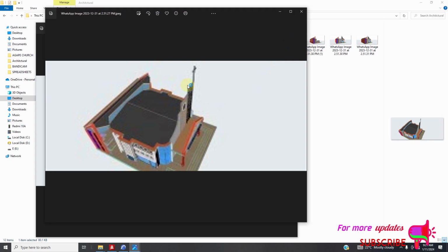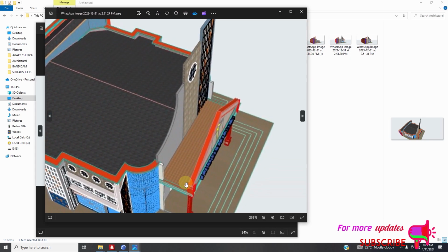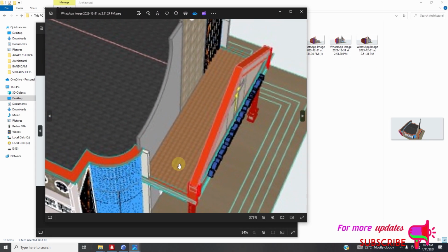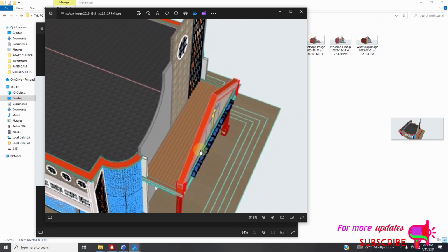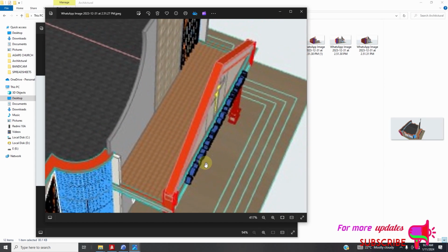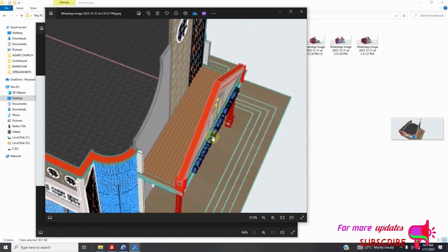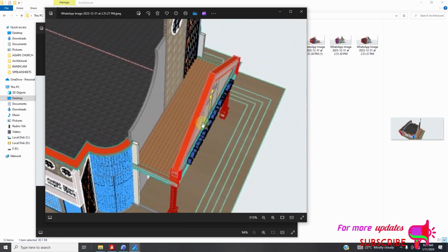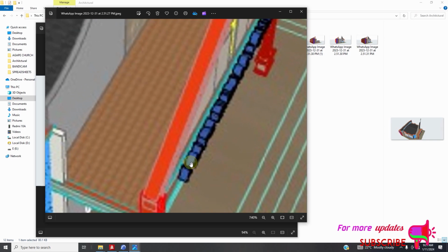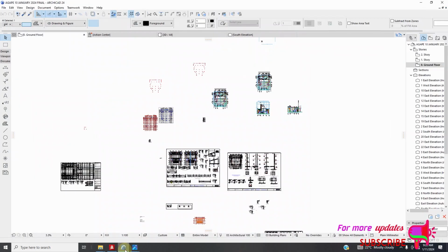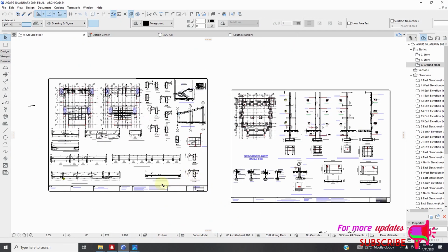Okay, so I think this one is just a roof, so this one does not have a slab, and thank God, because I think this span is too long. You can see we have a load here, so we need to consider this dead load on top of this critical long spanning beam.